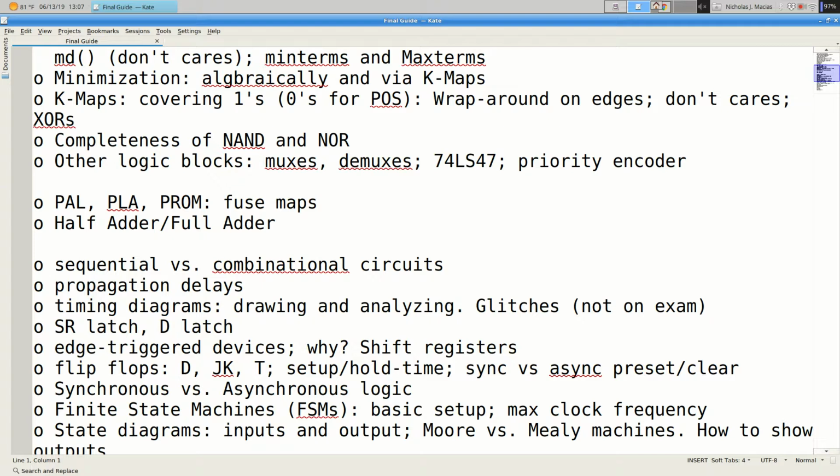And if we're laying these out side by side, we can make an n-bit adder by having n full adders, and the carry out from here feeds the carry in of the next stage. And if we're doing that, there's no carry in that comes in on the rightmost bit, so we can assume this is a 0. But rather than taking a full adder and tying that to 0, we just make a half adder, which is a slightly simpler circuit.